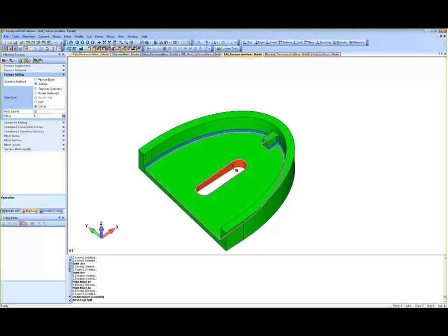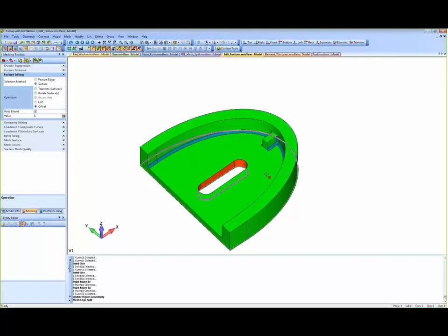So if I click right there, it moves in all of those surfaces by a value of 5, and essentially just offsets the surfaces that I was looking at. We can also do the same thing by selecting this surface where it moves it out. It's a very useful tool for very quick editing of your geometry.